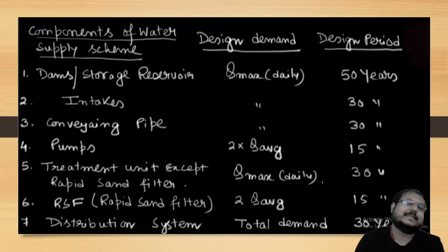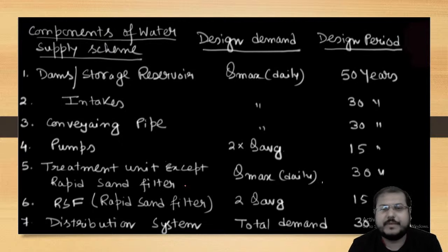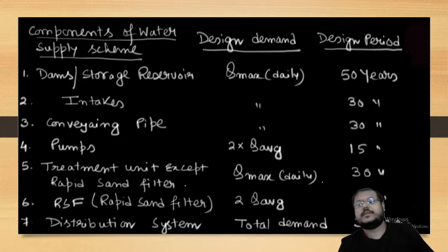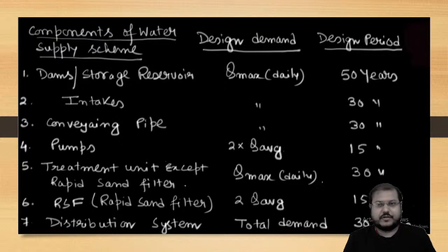Treatment units except rapid sand filter, RSF: apart from that, all the treatment units will be designed for Qmax daily and the design period is 30 years.